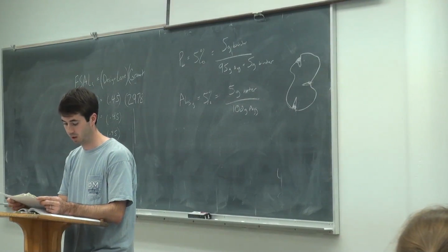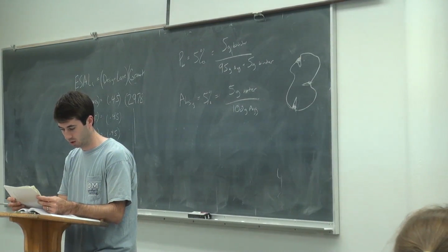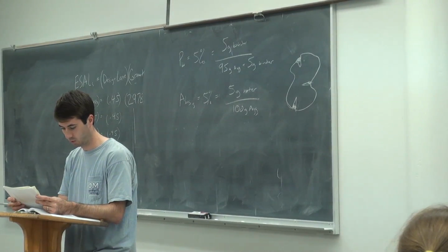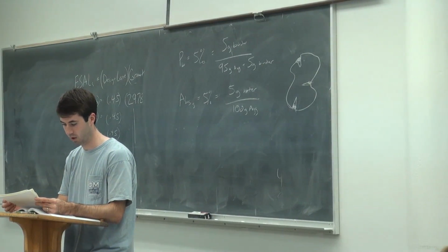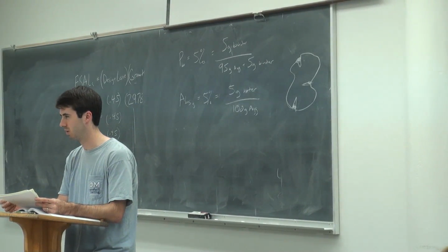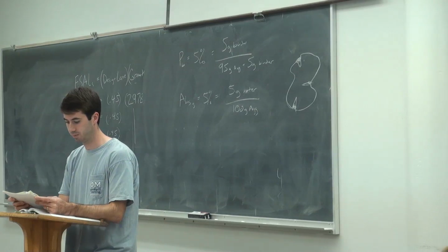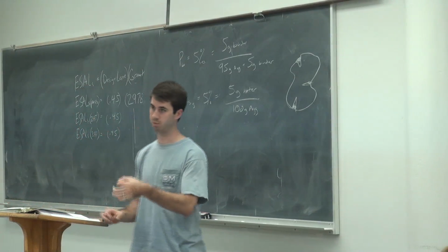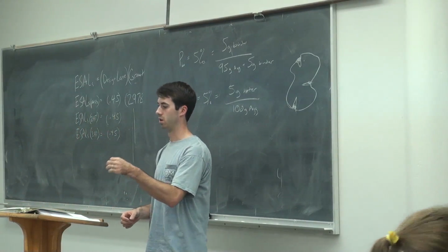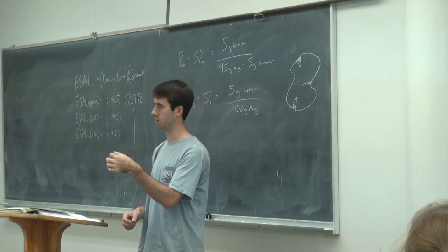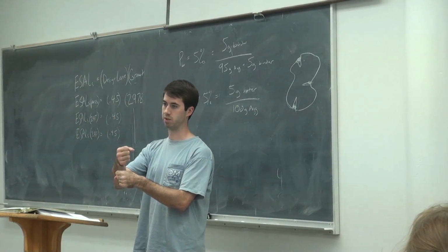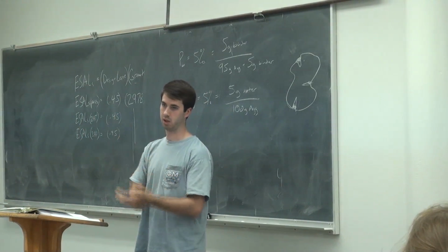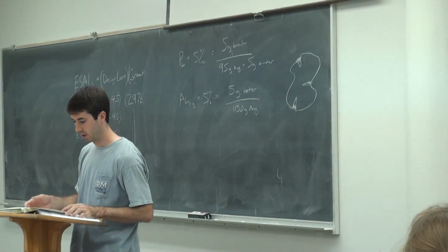Then after that, you run basically 4 different tests. Are y'all familiar with DSR? Have y'all talked about that in materials? What a DSR is? It's basically just, you put a little hockey puck kind of thing of binder, just like an inch in diameter, between 2 metal plates. They rotate back and forth, and it calculates a bunch of stuff.